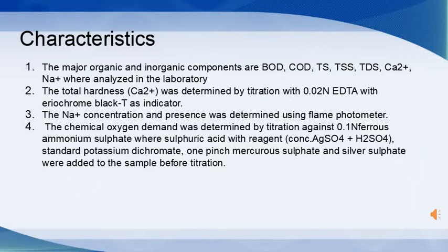The sodium ion concentration was determined using a flame photometer. The chemical oxygen demand was determined by titration against 0.1 N ferrous ammonium sulfate, where sulfuric acid with reagent standard potassium dichromate, 1 pinch mercuric sulfate, and silver sulfate were added to the sample before titration.